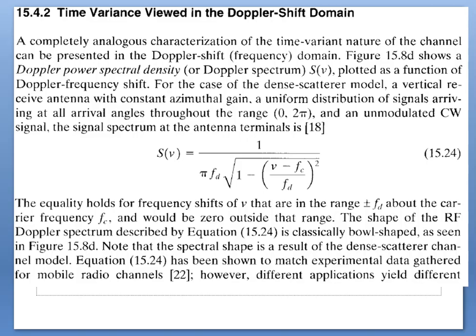For the case of a 900 MHz mobile radio, consider the typical effect of Rayleigh fading on the signal's envelope amplitude versus time. The figure indicates the distance traveled by the mobile in a time interval corresponding to adjacent nulls, which is on the order of wavelength lambda by 2. The time required to travel a distance lambda by 2, when the travelling speed is constant at v, is T0 equal to lambda by 2 divided by v, that is equal to 0.5 divided by Fd.